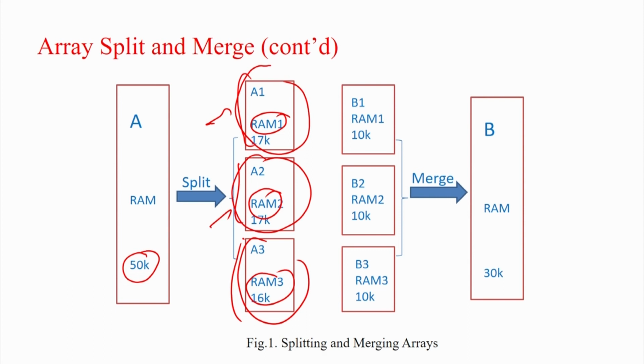Again, this is very design specific, it is not always possible, but you always try to keep in mind that if you have a very big array with multiple accesses, it might create a problem in accessing RAM or ROM. So, you can split that array into multiple small blocks, where the accesses to these are non-overlapping, in the sense they are not accessed in parallel, so that you can map them into different blocks.